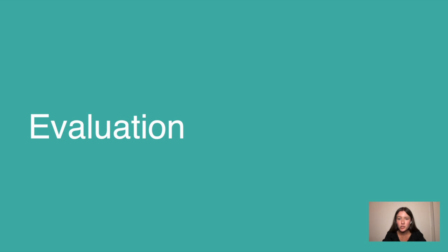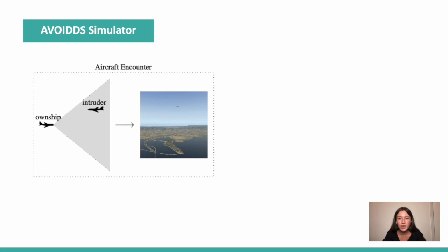The second major contribution of our work is the evaluation suite, consisting of standard metrics like mean average precision on individual samples, as well as evaluation on the collision avoidance task. To evaluate the model on the downstream task, we developed a closed-loop simulator that uses our trained models as part of our perception system. The initial aircraft trajectories are determined by a straight line encounter model that outputs step-by-step positions of the 2 aircraft over 50 time steps. All encounters generated would result in near-midair collision without intervention.